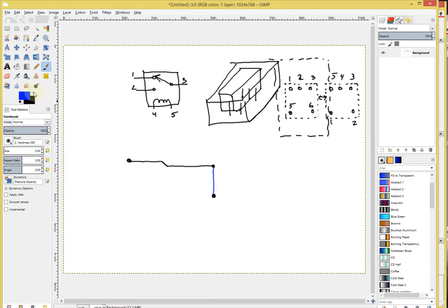Once again, if I'm on my top layer, and let's say I have another pin here, and another pin here, then I can come back down here. Suppose I'm blocked and forced to go down, so I insert the via here, then I move to the bottom layer, and go through there, then insert another via there, and move on to the top layer, and then do a horizontal move.